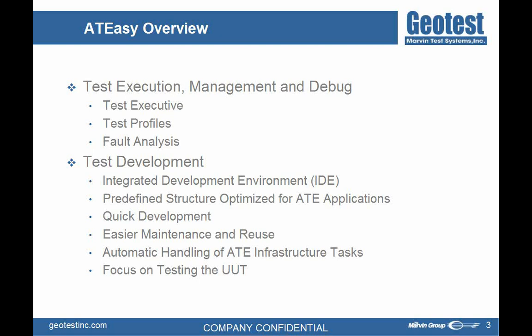Because of the integrated development environment, ATEasy allows for very quick development of your application by providing a structure for that development. It also makes it easier to maintain and reuse code in future applications. ATEasy has automatic handling of various ATE infrastructure tasks such as evaluating test results, reporting those results to the operator, and so forth. And what it does is it allows the test engineer to focus on testing the UUT as opposed to managing the overall test process.